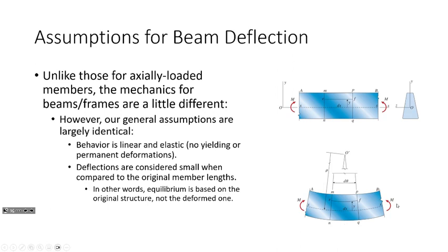Okay, so let's think about this from a structural analysis perspective. Let's say here's the beam, it's simply supported, and I put 20 kips in the middle. What are the reactions on either one of my hands? Up, and how much? 10 kips, right? Okay, so when you do that analysis though, you assume that the structure is rigid. You assume that the structure does not deform, right? Well, the structure actually does deform a little bit. What small deflection theory means is that the equilibrium of the structure is not affected by the deformations, okay?